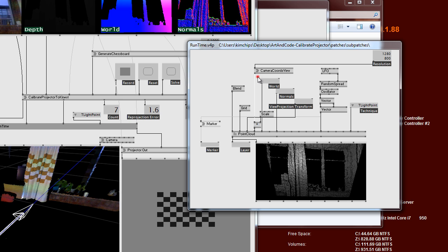And then, because we're working in camera coordinates in V4, we have to transform the renderer often, because our renderer is generally -1 to +1, and here we have to say this is 0, 0, and that's 1280, and that's 800, so this comes in this transform here, which gets applied to T screen, which is a special transform that I added to the shader. Okay, it's accepting some other things in the shader, like which technique to use. If I just go to normals now, this is in projection space, you can see. If I turn off calibrate, you can see that's coming out down here from the projector. You can see it's coming out of the projector there.